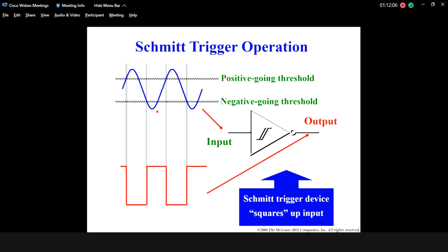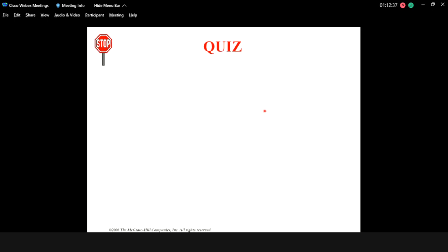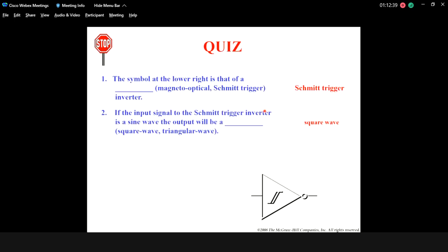And from this one, where can we use it? We can use it in terms of producing a clock. Let's say the clock is a sine wave oscillation from any natural oscillator. We want to make sure the clock becomes square. We can use Schmitt trigger operation to change the clock from analog to a square, digital clock.